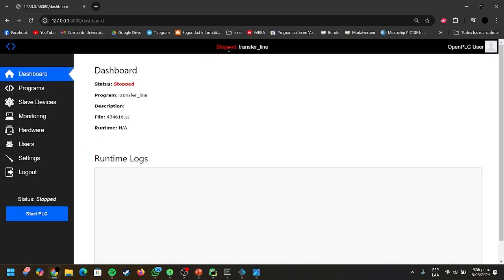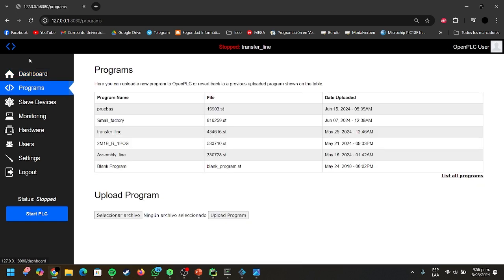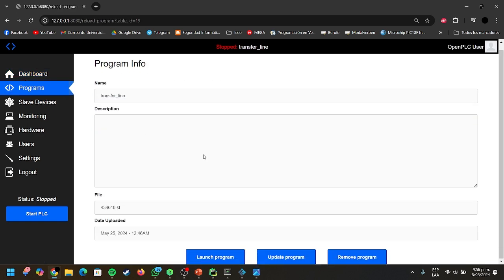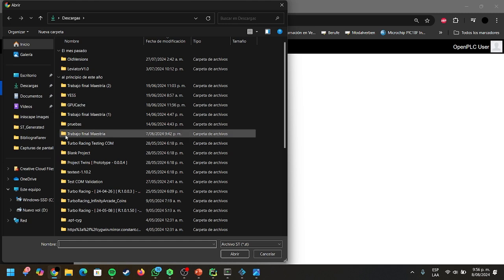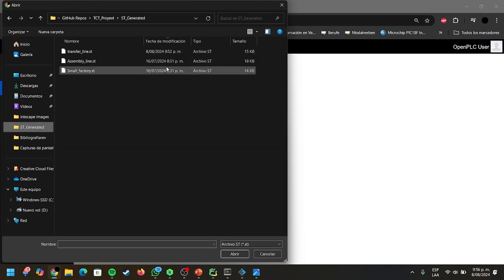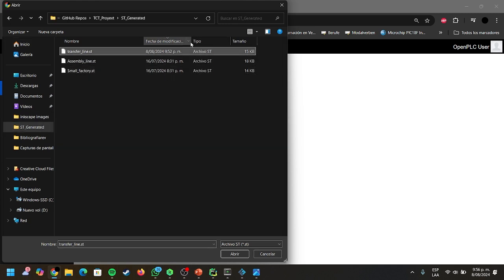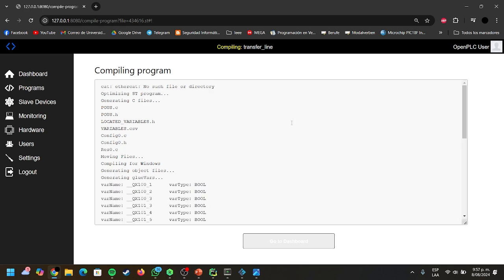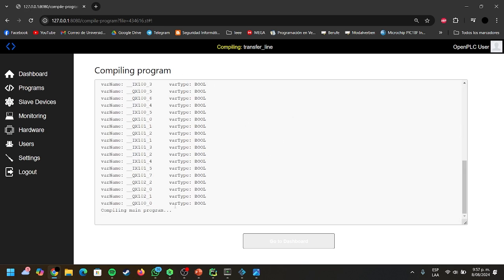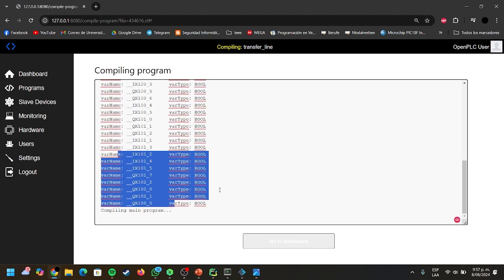We go here to OpenPLC, let's go to Programs, Transfer Line, update program, just to take the last code we created. Let's see, right here, upload the program. Give it a little moment so it verifies that everything is okay.